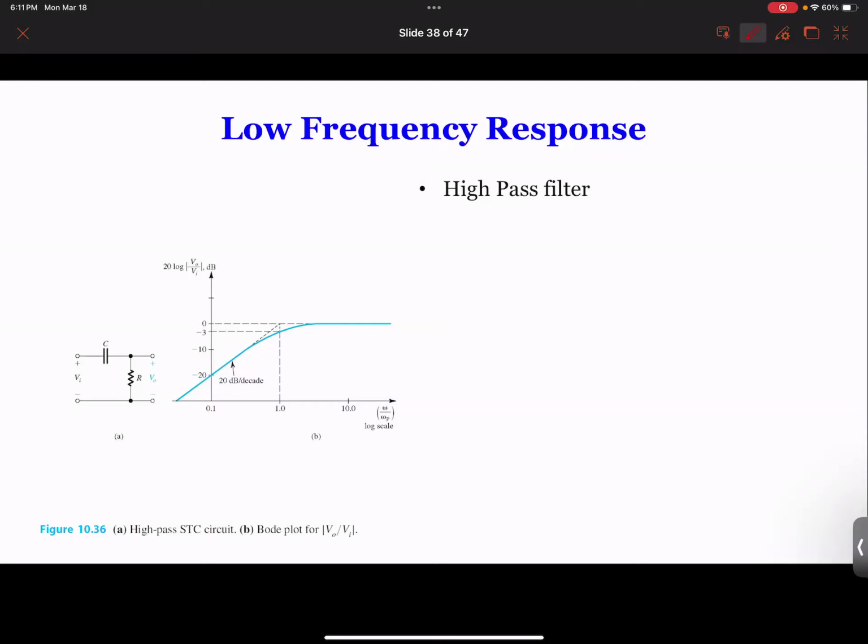Sweep means the circuit is going to do simulation for all the frequencies for you, and it tells you the ratio between output and input. So you can set your frequency band, like the sweeping range from, let's say, 0.1 Hertz all the way to 1 gigahertz, and you can see your output. But if you don't have your capacitors connected, it might not give you the middle band. It might give you a flat line. So you know that your circuit does not have any capacitance.